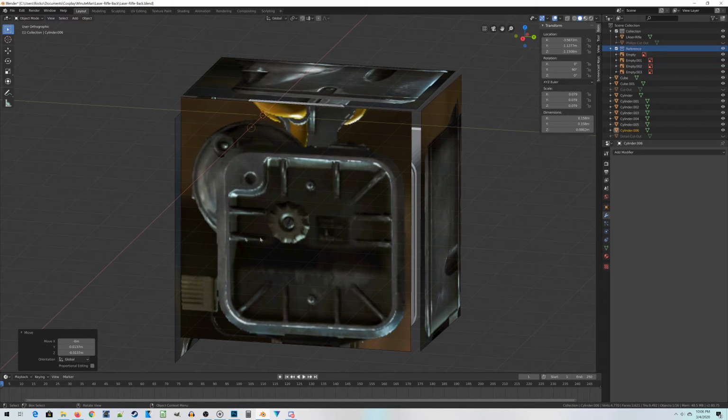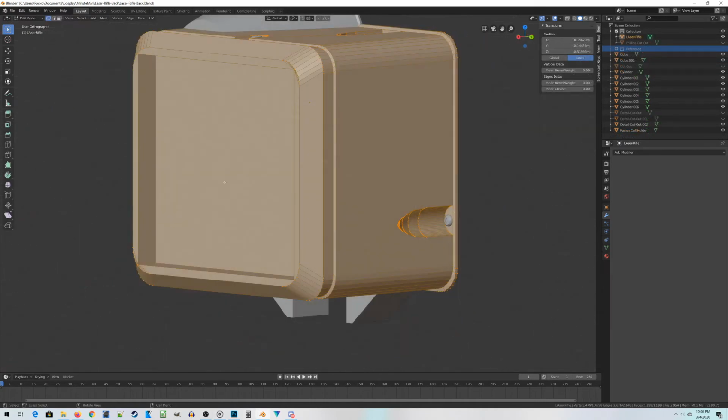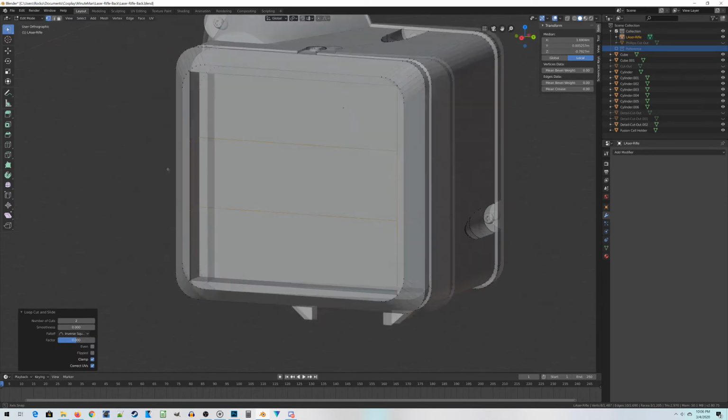So there's actually two insets right here. So let's figure out how we're going to model that. And our solution is probably going to be the loop cut. So do Control R and move your mouse cursor around, and eventually you should see a yellow line like this. It's actually mimicking the cut we want to do. Use the mouse wheel to make two of them, then left click, and then left click again.